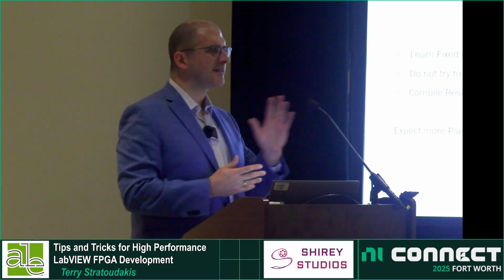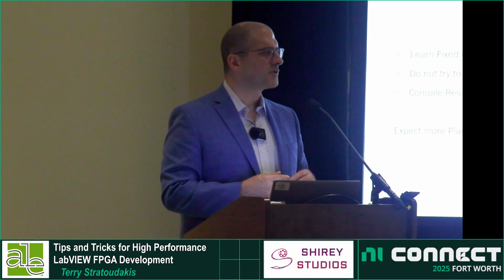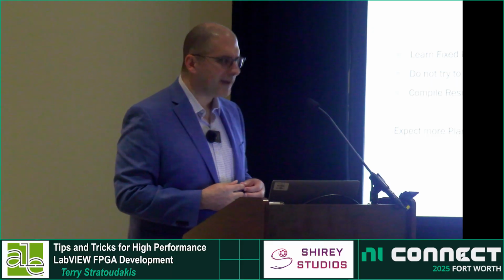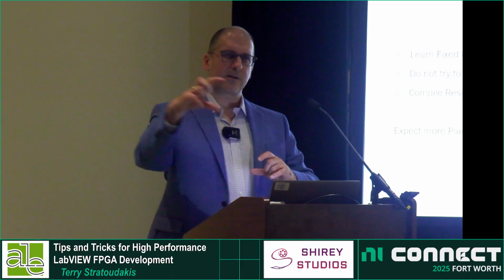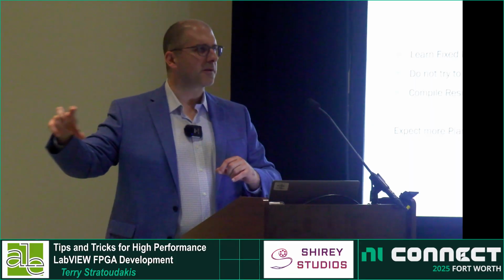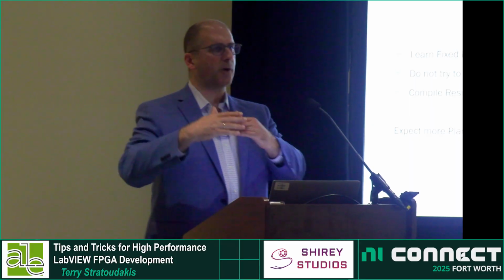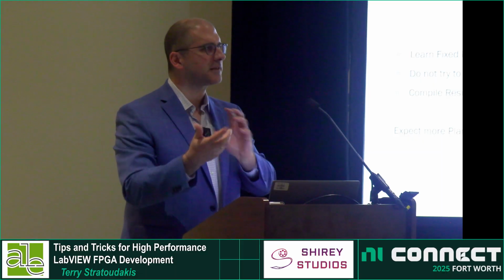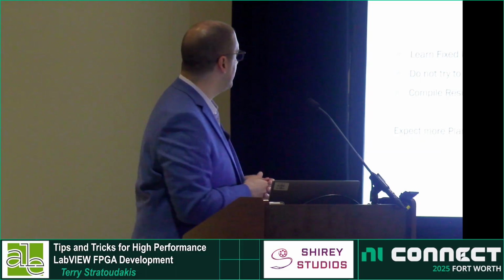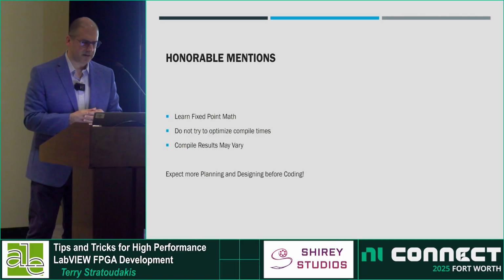So that's another extra skill to be developed. Generally, the skill that gets developed with fixed point math is range analysis. What's the range of the data here? And so forth. And that allows us to specify how big the fixed point value is going to be, like a number of bits. You have to specify how it's going to be configured.